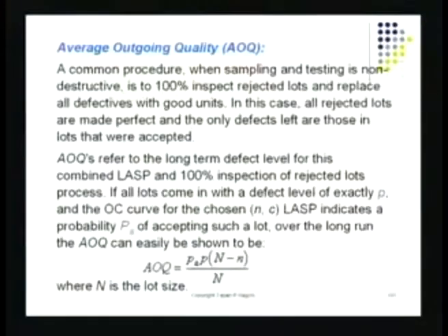A sampling plan is very powerful when it is able to reject most of the lots that are somewhat away from AQL, so it approaches the ideal curve. In fact, by increasing your n or by reducing c, the effort should be to approach as closely as you can the ideal curve. If you can approach the ideal OC curve, you are doing the best that is possible.